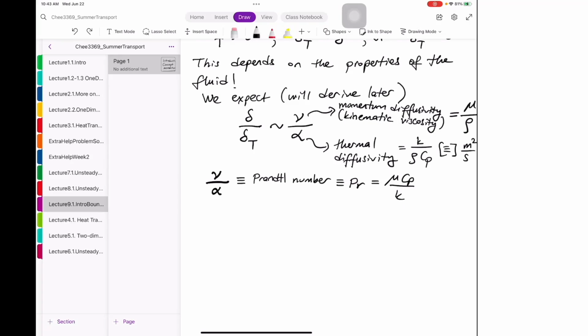If I get, for example, Prandtl number 0.2 in the US with US units, I get exactly the same number 0.2 in Turkey. That's something miraculous. That's why we like to work with non-dimensional numbers, because they are universal, and it doesn't depend on your selection of units.